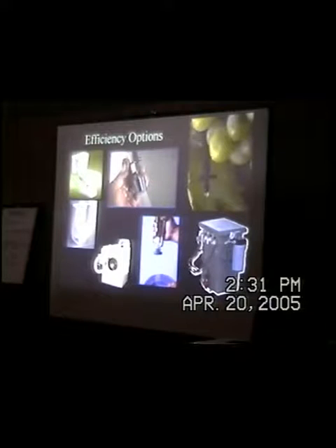This is a big one. X-ray machines usually use once-through cooling, so you save 90-something percent of the water by going with a recirc cooling system for X-ray machines. Same with some other technologies. This is a spray valve. We're giving these away door to door to restaurants in California right now, often in restaurants where it just runs continuously. So you're saving a huge amount of hot water energy as well as the water just by installing those.